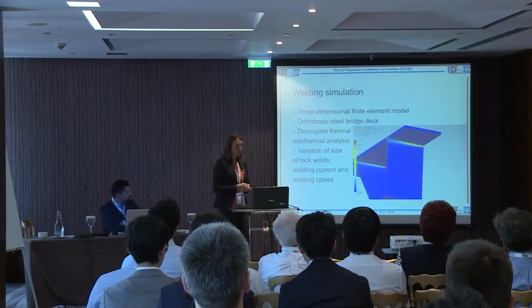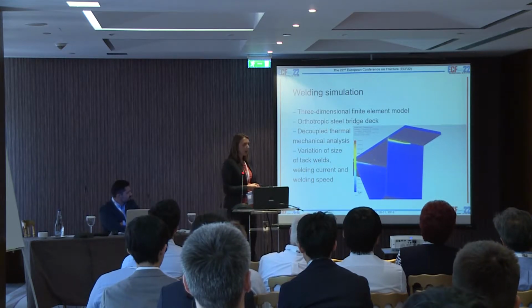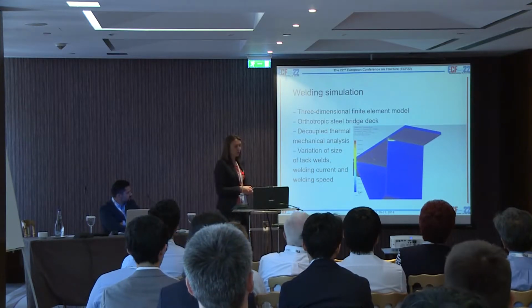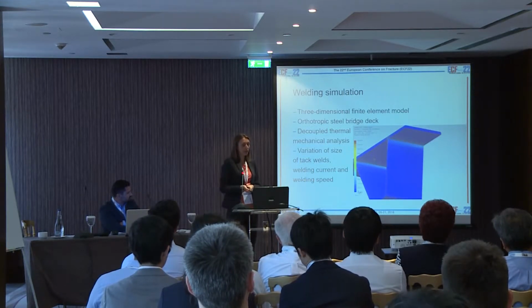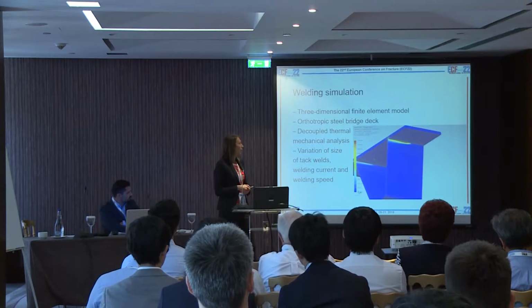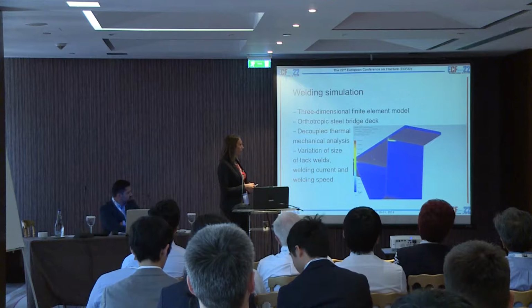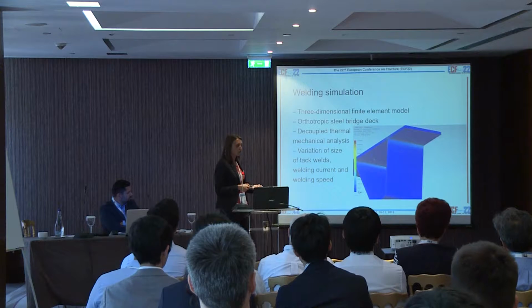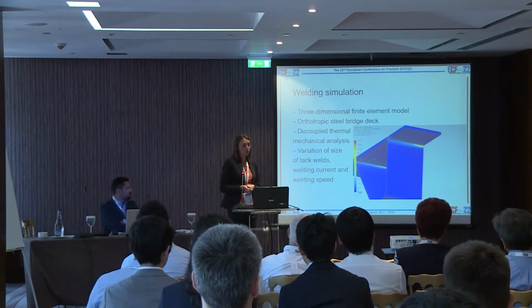In order to have an idea about the residual stress distribution for an orthotropic steel deck, we made a three-dimensional finite element model which simulates the welding procedure. We investigated the weld connection of longitudinal stiffener to the deck plate. We performed a decoupled thermal mechanical analysis. During the thermal analysis, you can see over here, these are the temperatures which are introduced during the welding. And these temperatures are used as a time-dependent load for the mechanical analysis in order to determine the residual stresses.